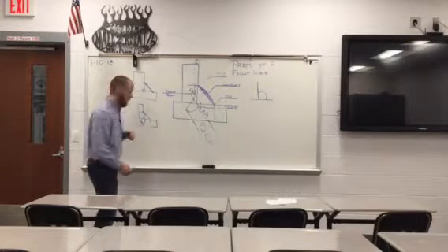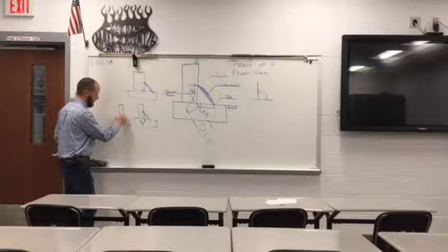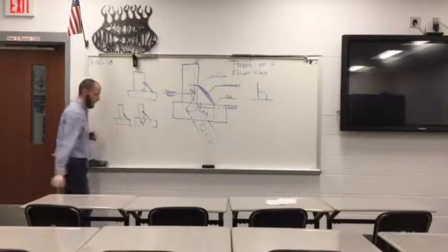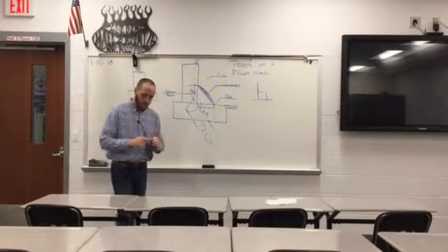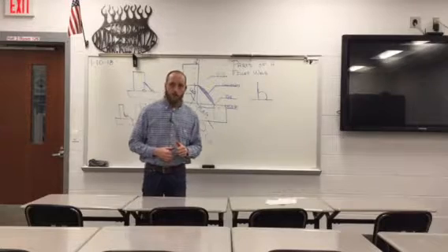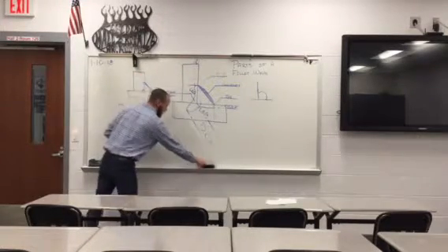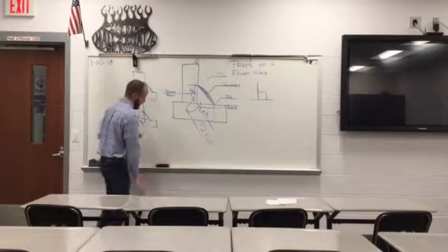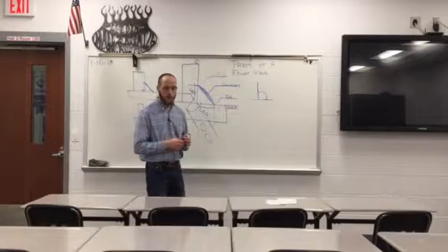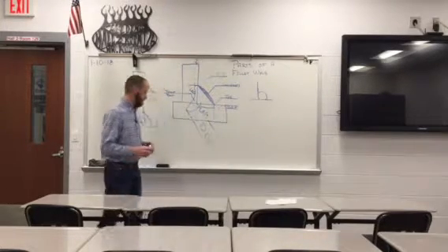If we have a concave weld, where the weld metal is sunk in without weld convexity, not a straight line, you have insufficient effective throat thickness. That's a huge problem in strength calculations. If they call for 1/2 inch of weld material and it's not there and you don't have that effective throat thickness, your yield strengths are going to be much less.